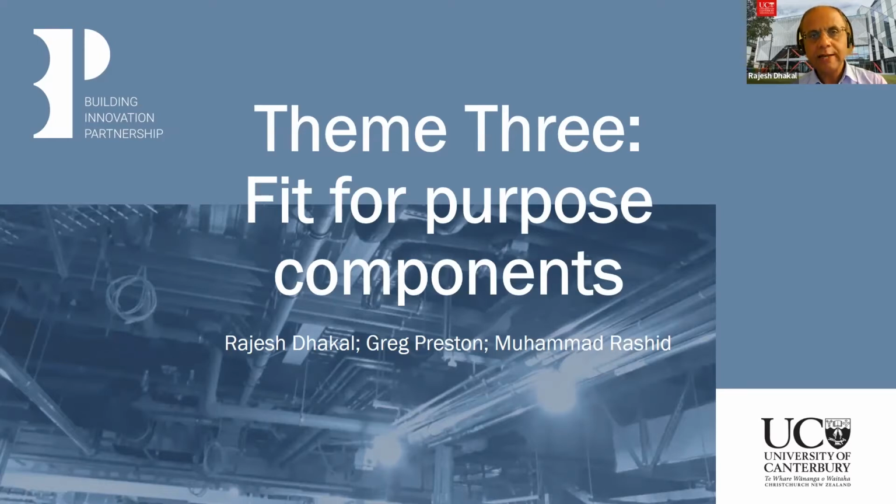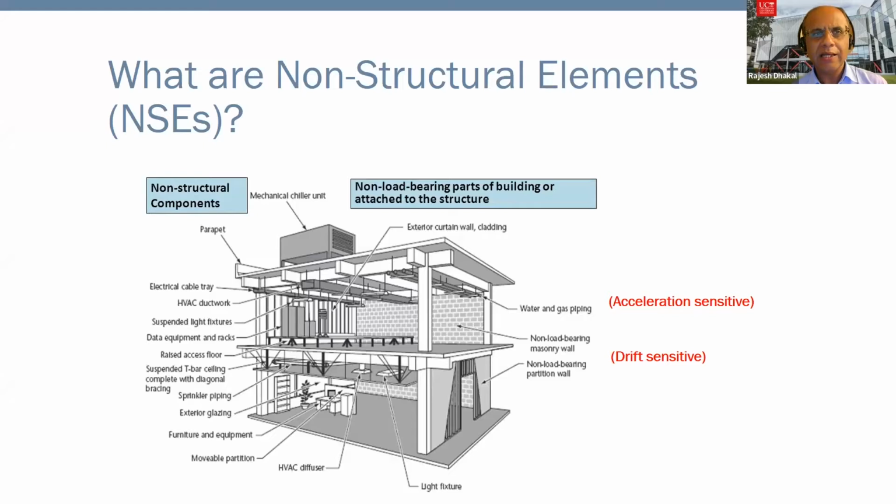So let's start. This will be like preaching to the converted, but just to give you a brief overview of what non-structural elements are: the scope of the theme is anything in the building, any part of the building, that does not participate in the gravity and lateral load transfer. For example, the structural system, which is beams, columns, slabs, foundations, they are the structural members, and anything other than that, that does not participate in this load transfer, we call non-structural elements.